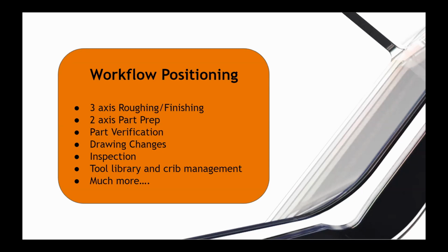So really where Fusion will shine at this particular junction is to have your stock and raw billets all set up, and use Fusion 360 to get a lot of the roughing and pre-finishing done. And you can leave stock, and make sure you add proper locating features, so that when your stock moves from machine to machine, everything will still be in place.